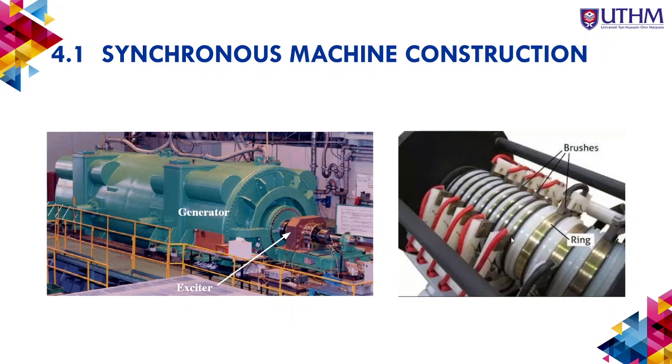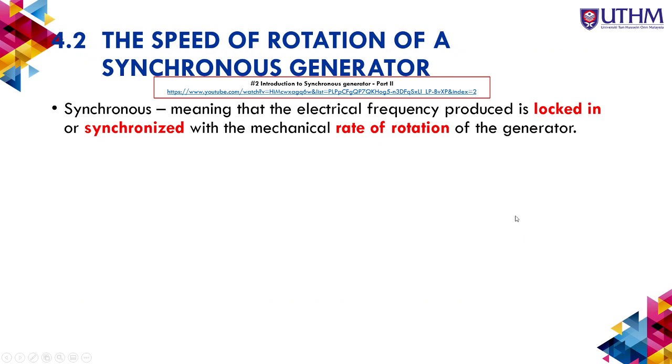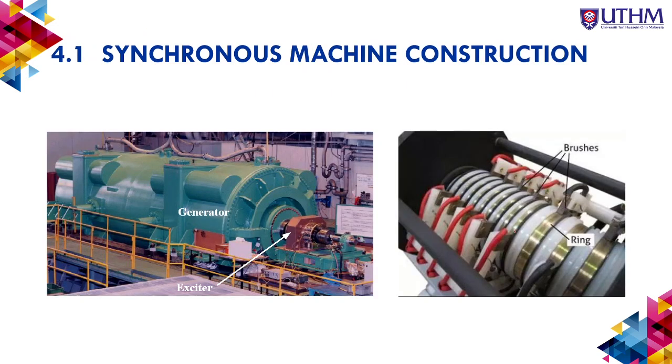The problem sometimes when using a DC brush is that when you touch it, there is oxidation, so the contact has a problem. Sometimes with a DC motor, when you first buy it, it is fast, but after being used for a long time it becomes slow. Because of the contact, you need to buy contact cleaner to remove the dirt, the carbon.